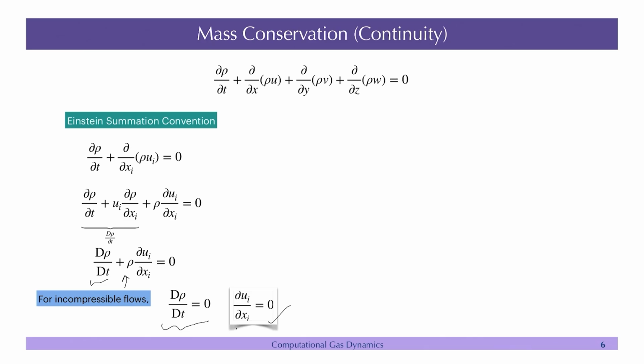So, what you will note here is that here we had the time derivative and change in density with respect to time. Now, since the density is constant, the time derivative goes away. What was a dynamical equation now becomes a constraint on the velocity, there is no density here, right. So, you might have seen the other form which is del dot u is equal to 0, right. This is the divergence free condition in the incompressible flow.